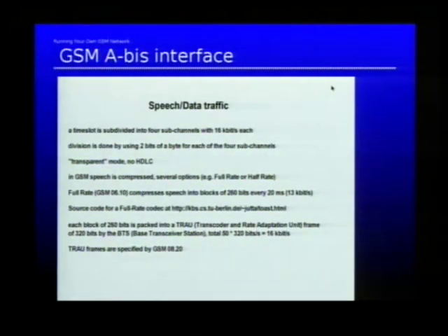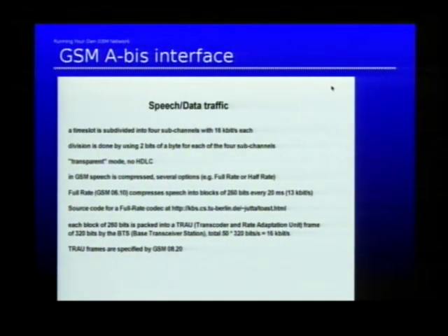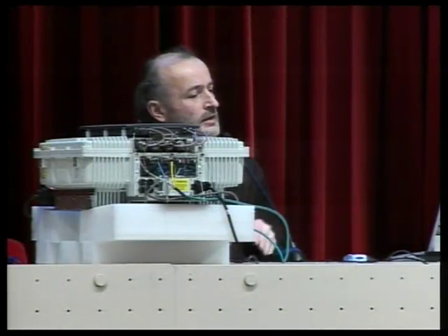Speech is different from data traffic. It's transmitted all the time. If there is no speech, you receive some sort of idle frames. There's nothing inside. It just tells you no speech is going on. Speech traffic is handled in one of the time slots we have in the ISDN channels, and you can configure the time slot which is used for transferring speech or traffic.